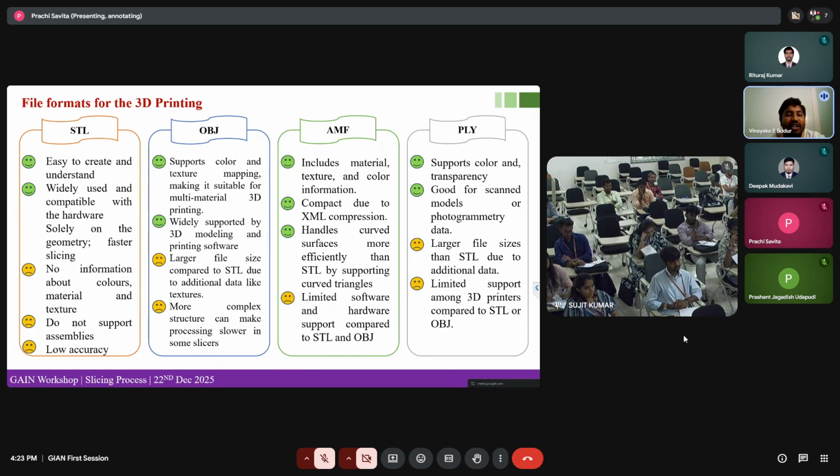The multi-file structure introduces significant logistical challenges. If the MTL file or the texture images are missing or incorrectly referenced, the visual data is lost, leaving only raw geometry. When I say MTL, it is referenced by the OBJ file itself, and it gives material properties and the texture images needed for printing. Additionally, the inclusion of high resolution texture maps significantly increases the file size and the computational load required for slicing.